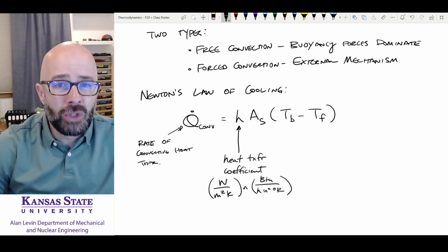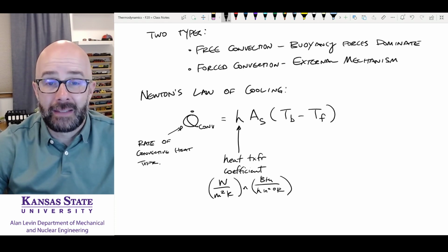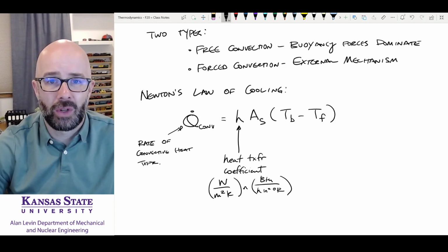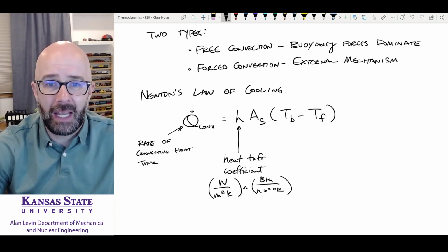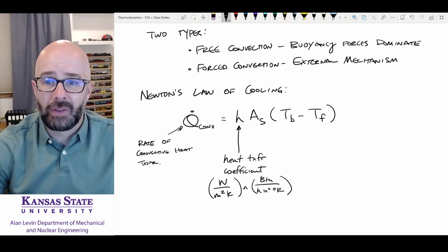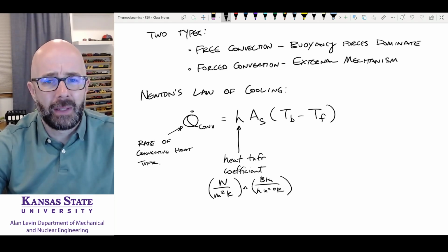Smooth surfaces and rough surfaces, the temperatures of the air, all of these things change the heat transfer coefficient. It is a complicated matter. It's not just something where they say, oh, it's aluminum, it has this heat transfer coefficient. Is the aluminum smooth? Is there turbulent air going over the aluminum? We have to know all of that information.